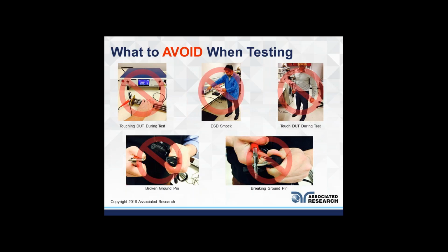It seems like an obvious thing not to touch something under test, but they don't realize that the voltage you're testing at is pretty high, and the current that it could output is lethal. I mean, 10 milliamps of current is definitely something you will feel. That is an electrical current that you could feel.